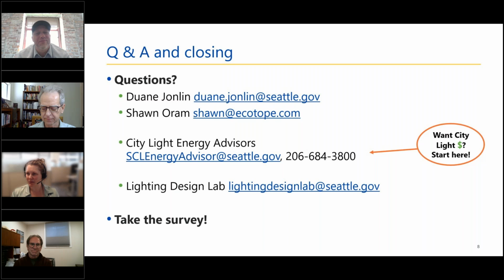Okay, and then Shawn, I think you touched on this briefly, but what implications does having an oversized mixing valve have? Yeah, we kind of touched on that, but most automatic control valves have a sweet spot where they perform well. What I call that is valve authority. If your valve has good authority over the flow range and you've sized it right, then you're going to have really steady mixes. But you'll know right away if your mixing valve is oversized, because it'll hunt all day.